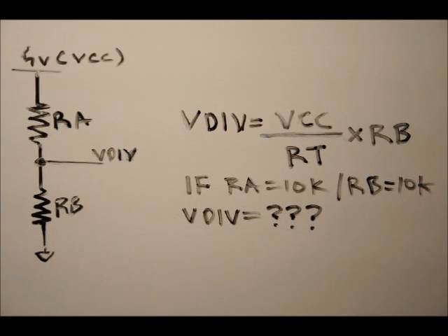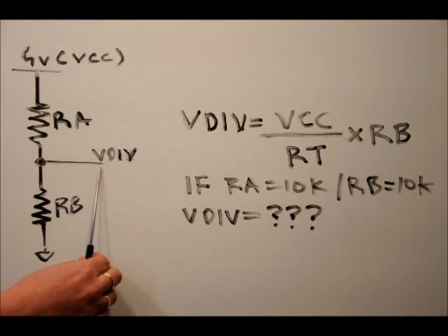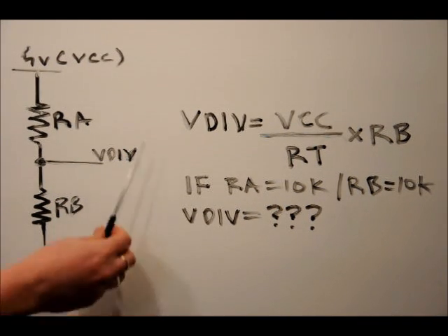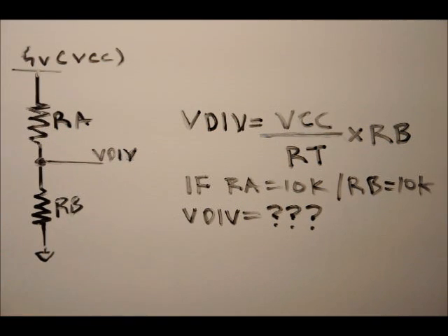Before we get into this laser tripwire circuit or light sensor circuit, we're going to need to go over our resistor divider theory. So this is our standard resistor divider, and we use that to create specific voltages right in between. We're going to call the voltage in the middle of the divider VDiv, for V division, the voltage at the dividing point right here.